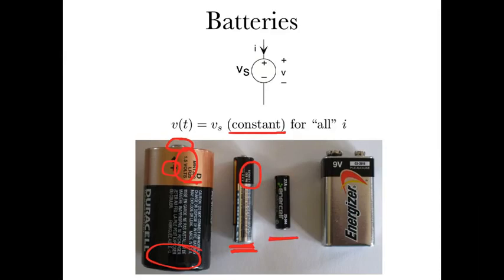Wanted to point out, I discovered this the other day. This is a battery that goes into my remote control for my door lock on my car. And if you look at it very carefully, right there it says 12 volts. So this actually provides a bigger voltage than a AAA, than a D cell, but it doesn't provide much current. By the way, the 27A that you may see at the top of this battery is a model number. It does not mean it provides 27 amps. I guarantee you it doesn't. And finally, this rectangular battery, you see, is clearly labeled 9 volts. And on the side, you can look to see which end is positive and which end is negative. That's labeled on the side of the battery.